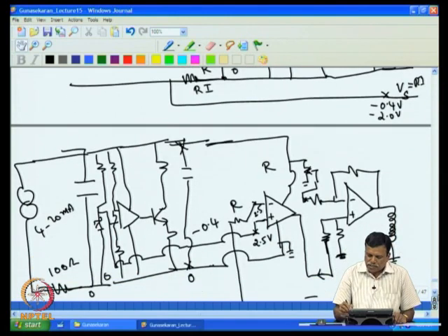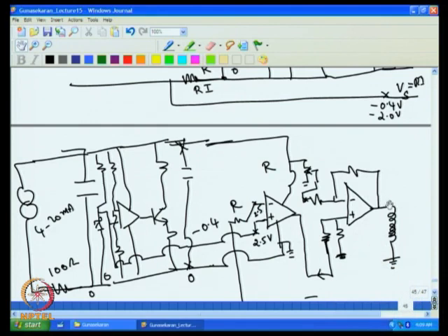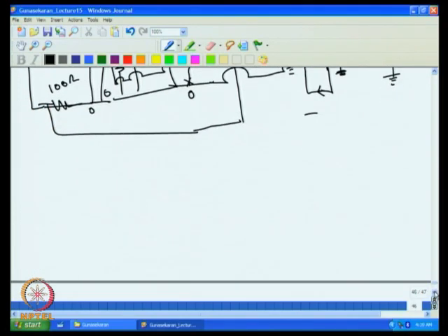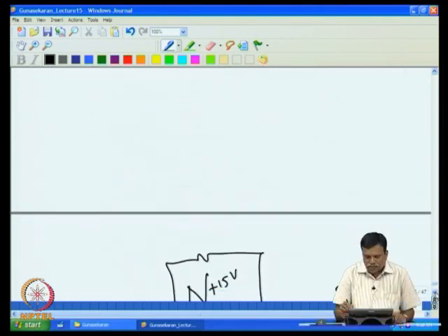So for example in this case there will be some output voltage. If you don't want that output voltage, then we have to make sure that the extra voltage whatever is coming is not driving this. One popular way of solving that is to put a Zener, so that the minimum voltage whatever is coming from the op amp is dropped across this Zener. So this is one of the important observations we have to make in terms of usage of operational amplifier with single supply.